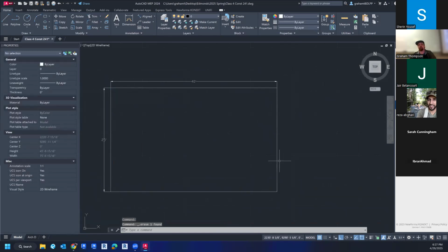And that essentially was exactly what we were talking about, right? Where you take a line and you copy it 6 inches down, you copy it 6 inches in, you copy it 6 inches up, right? Same concept. And since these were all individual line segments, we had to do it 4 times, right? One per line. So let's do that one more time. Again, it's going to ask to specify a distance. Since I already specified 6 inches, it remembers that. Okay, I'm going to go ahead and say enter. That's what I want. Select the object. Okay, and I'm going to go ahead and click the line that I want to offset.